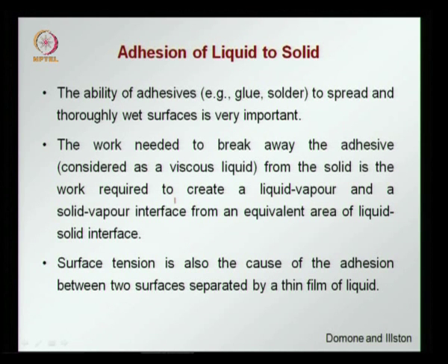And we can also imagine that how the adhesive works is by creating a liquid solid interface, and in order to break that we need to expend a lot of energy. If we think of the adhesive as a viscous liquid, to break that bond between the adhesive and the solid, we have to create a liquid vapor and a solid vapor interface instead of just a liquid solid interface on the equivalent area. So this requires some energy, and that is why we need to expend a force to break what has been adhered or an adhesive made joint.